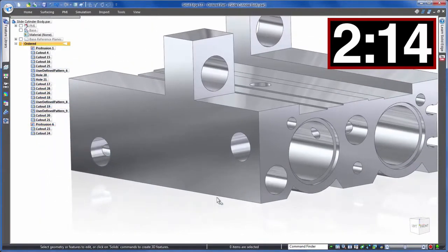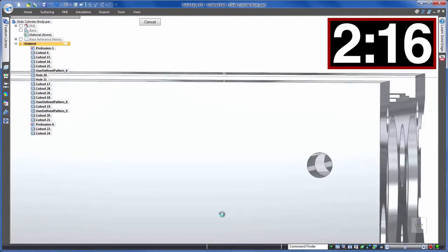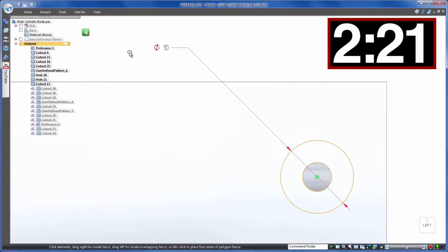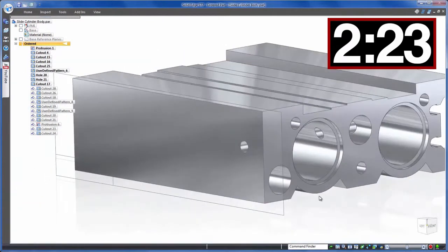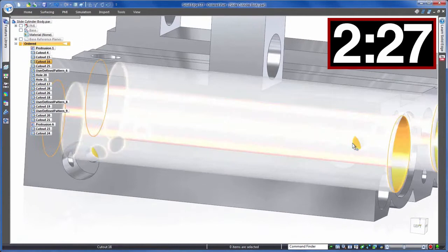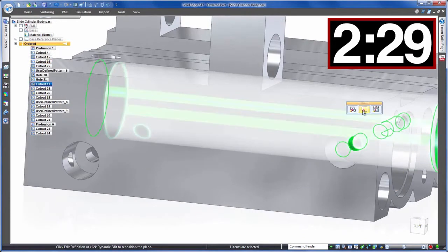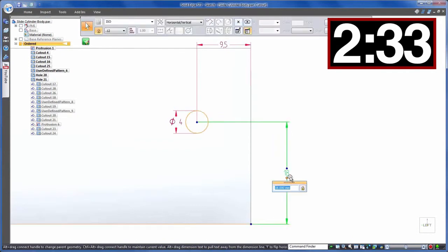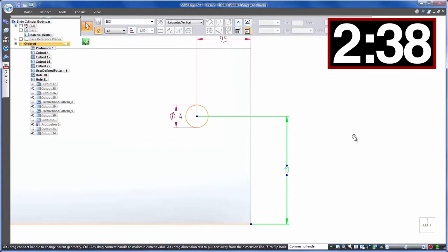We need to do the same with the top counterbore to total our required 2mm clearance, but repeating the same steps, notice that this wasn't created in the same way as the previous. Instead it has two cuts, one concentric to the other. These sorts of frustrating situations are often run into in history-based modelling. Design intent may not be what you'd naturally expect. It's all down to the original decision and creation. Another fix required.